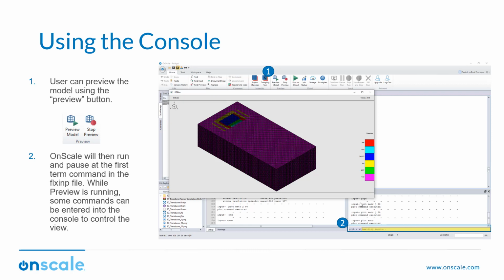Then this console command will become activated, allowing you to enter some new options on the run. So you don't have to preview, stop, change the code, preview, stop, change the code. You can preview, input your options, and replot without having to relaunch everything every time. This is important because for this model, every time it's run using preview, it has to remesh everything. If you have a big model which needs some time to be meshed, I don't want to remesh it every time.